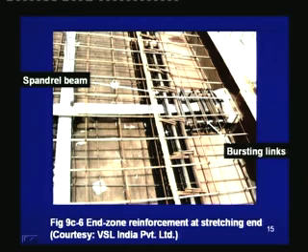This photograph shows the end zone reinforcement at the anchorage end of the prestressing tendon. Bursting links are provided to resist the stress concentration that is generated after the prestressing operation.